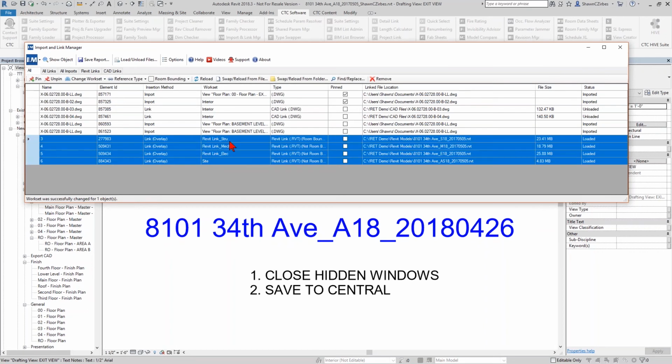I'm also noticing that none of my Revit links here are pinned, and they all really should be. So I'm going to go ahead and pin all of them. I don't have to, again, go track down the actual instances of these in my model anywhere. I can see their pinned status of each instance right from here, and I can modify that straight away. So the work sets I can modify, the pinned status I can modify, assuming they're in the right place, of course. If they're not, well, then people can unpin them and move them and hopefully repin them.